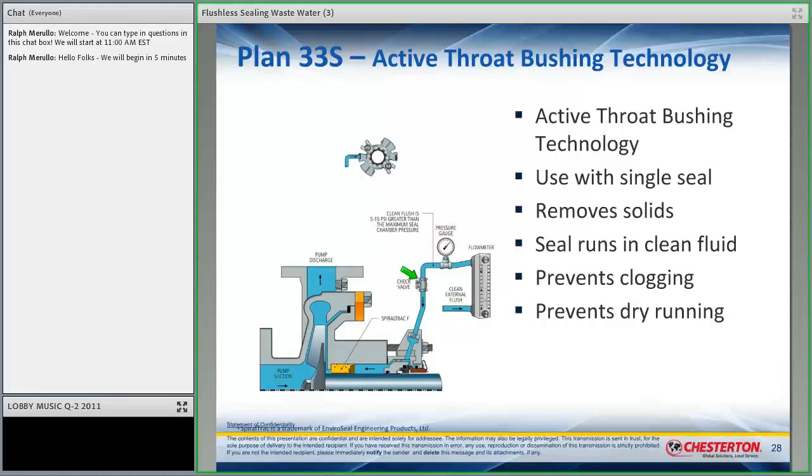Absolutely. So this is an easy way to set up an insurance policy with your spiral track and with your split seal, hard face or not, in wastewater service, right? And particularly in vertical service, right? And so there are situations, and I'm going to share one, where in vertical service, it takes time for fluid to find its way up to the seal. And what we do not want is the primary seal to run without face lubrication, lubricated face seal, right? So setting up this plan this way really eliminates a flush, but provides, we'll call it start and stop lubrication, right?